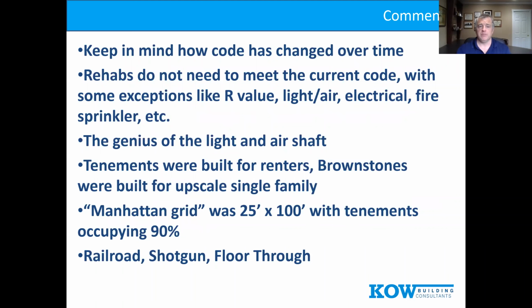Generally speaking, your rehab, your renovation doesn't need to meet the current code with some exceptions. So you start doing this renovation, you say, well, what do I have to meet for new code? Typically, some energy efficiency items like R values, light and air requirements, electrical, fire sprinkler, but that existing building could stay where it is for the most part and be what we call, it's a long way of saying grandfathered, pre-existing legally non-conforming. You're grandfathered in. You don't have to change it.